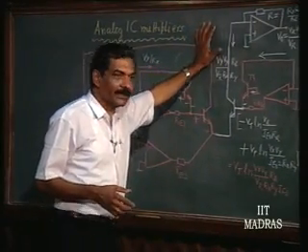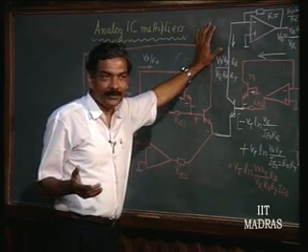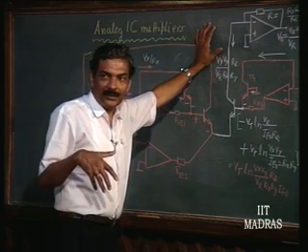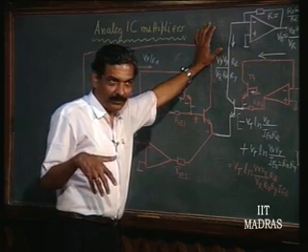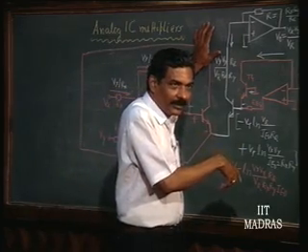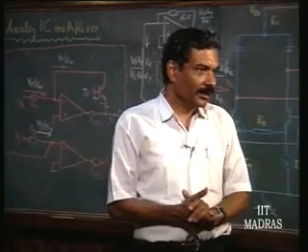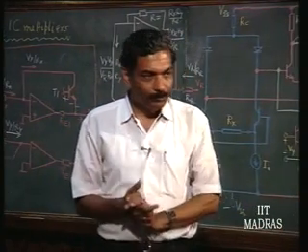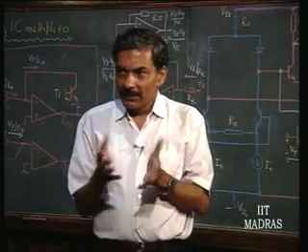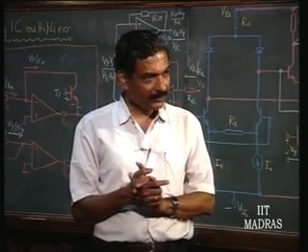The only disadvantage of this is that it is using op amps to convert voltage to current, and therefore the frequency of operation is going to depend upon the op amp compensation. And therefore, it is going to be limited to low frequencies, which is the limiting thing for the op amp. So, its limitation is only for the op amp, not for the basic idea of multiplication.